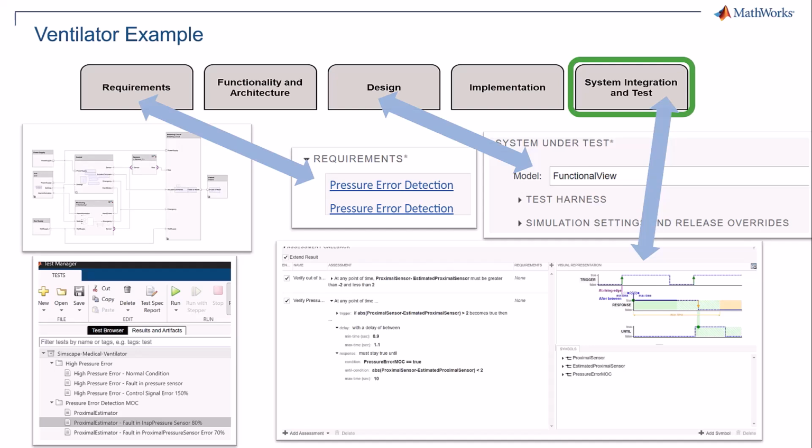And finally, you can verify your most critical requirements, those that come from your FMEA, at an early stage, long before your prototypes are built. If you fail to correctly investigate your need for redundancy, it will be costly to add the redundancy at a later stage in your project. As you can see, each test case in the Test Manager has links to the requirements, the design, and also the fault to be injected. Your digital thread is safeguarded throughout your project, and it also includes the FMEA.